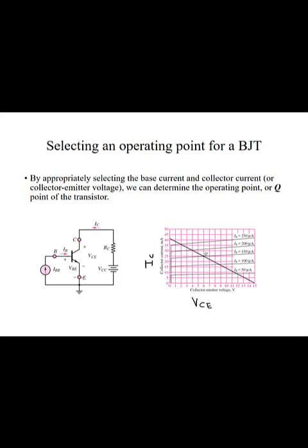In order to find the voltage between the collector and the emitter, for example, in that specific example, we have both VC and VE, so we can easily find it. And the other thing is that we have to find I collector, and for finding the I collector in this specific example, we can see that I collector is the voltage at this point minus the voltage at this point, so we're gonna have VCC minus VC over RC.